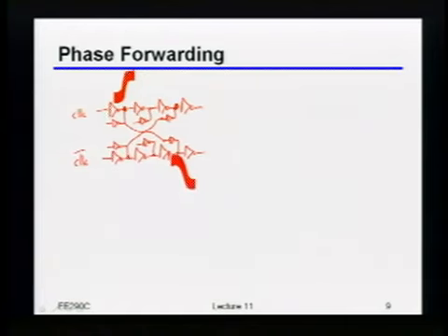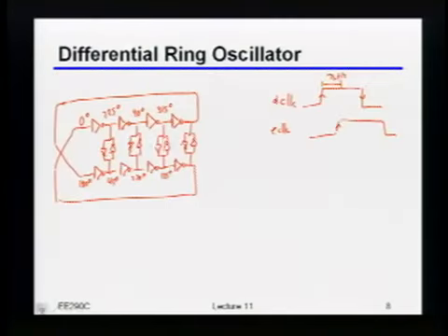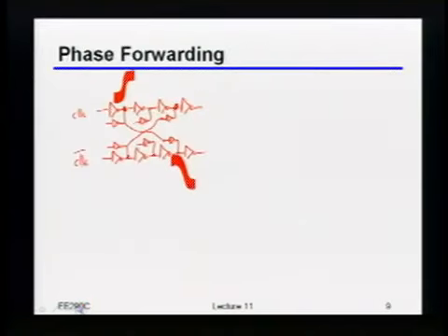Okay? It's almost like we're predicting that it's going to have to move eventually. Yeah, Charles? But would that actually mess up your duty cycle even more, because right now it really depends on the ratio of these two paths? Not necessarily. Again, it depends on how you size things, because remember, at the end of the day, I'm going to close this into a ring. Right? So everything is going to be sped up on both edges because of the coupling that I'm doing. So it's not necessarily going to change the duty cycle much more than this one did. I guess my question is really about how do you actually size this main inverter and this...